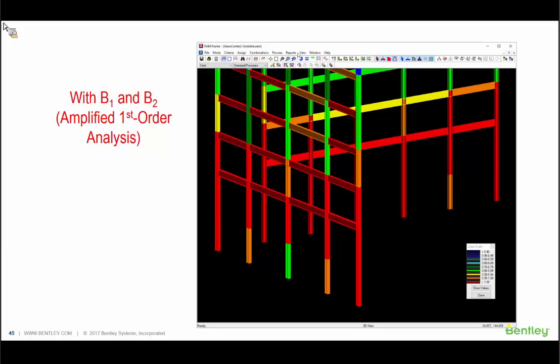It's still providing us a design with the first story piece of the column, and it's providing us with a design for the second story of that column. And so that's the reason for seeing two different colors in this particular column. It's because in the model, because of a partial story at that mid-height level, the program is providing us with the design of the two different pieces of column.